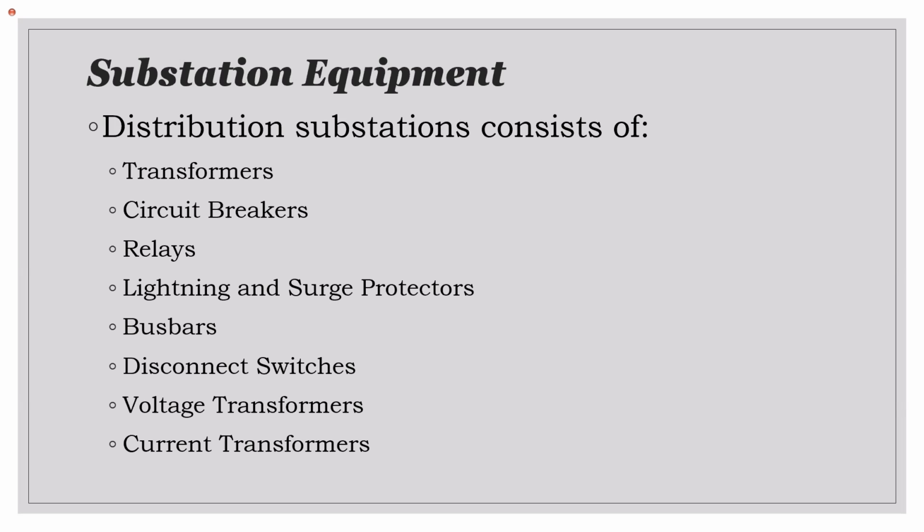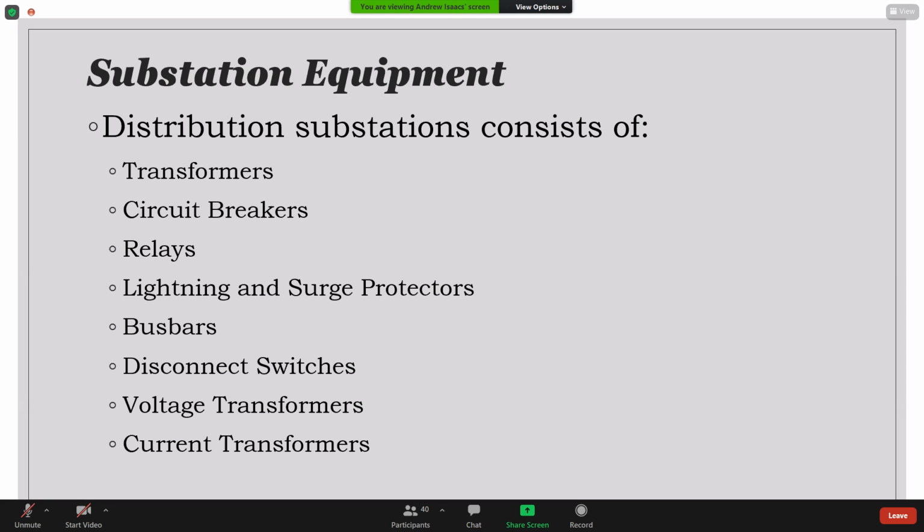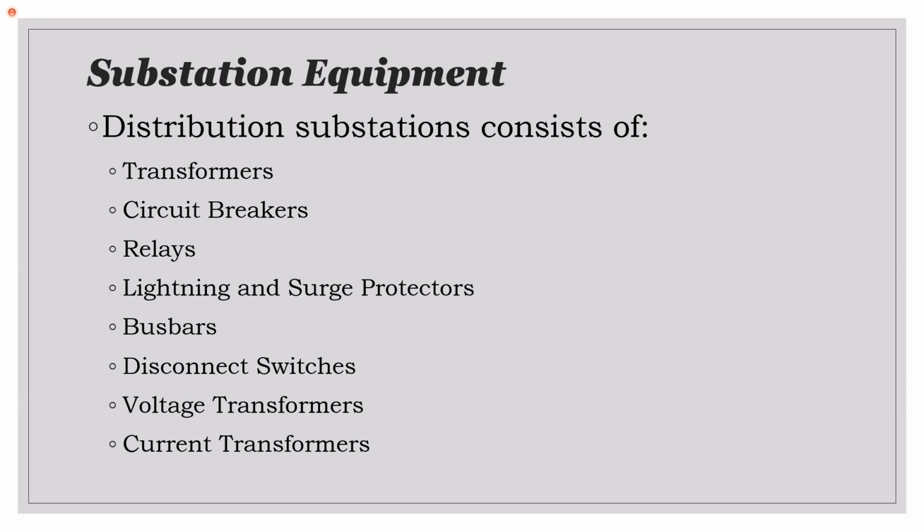So those voltage sources that you may have seen in a circuit that we did in networks, those sources are really generators, and those generators are connected to a bus bar, which is a node, and between those nodes you have resistance and you have inductance. Yes, I throw some capacitance in there too. And those may represent the lines that go between the generation and the node.